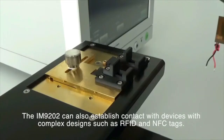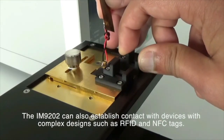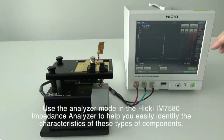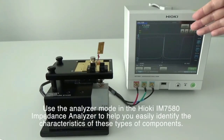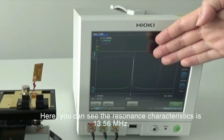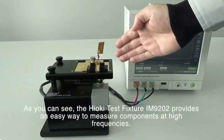The IM9202 can also establish contact with devices with complex designs such as RFID and NFC tags. Use the Analyzer mode in the Hioki IM7580 Impedance Analyzer to help you easily identify the characteristics of these types of components. Here you can see the resonance characteristic is 13.56 MHz. As you can see, the Hioki test fixture IM9202 provides an easy way to measure components at high frequencies.